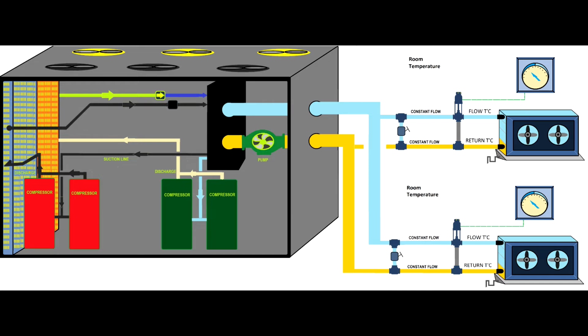Also, you can look at these actuators, at the valves, to see if they are closed or open, but that's not really what you look at. Because if you look at, as an example, the cooling agent flow temperature, that should be cold, almost as cold as it is at the origin.